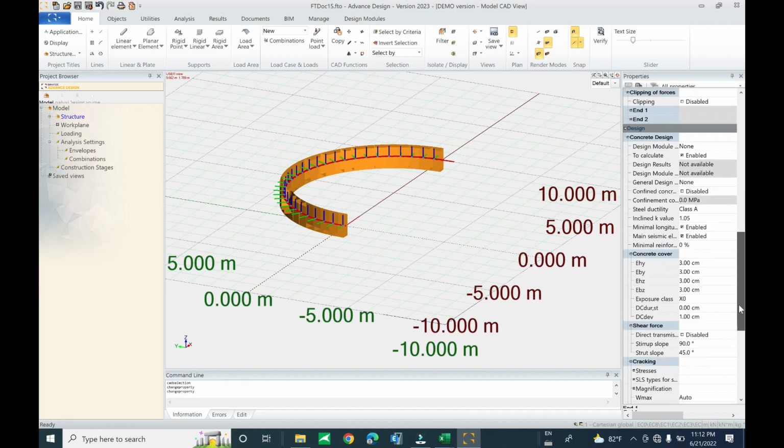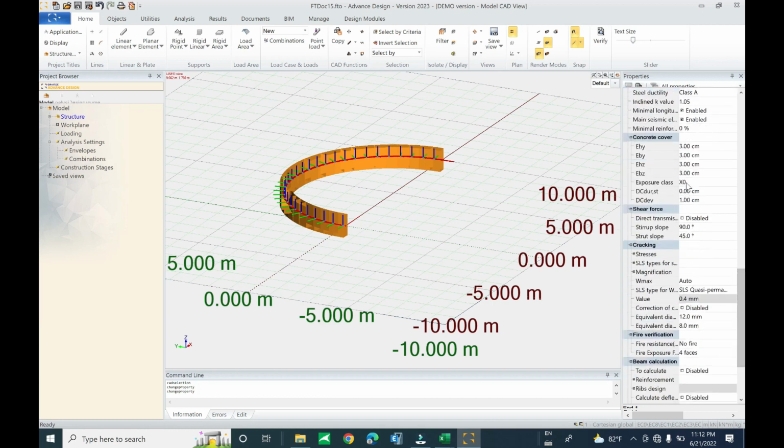on the concrete cover. Now we want to keep the concrete cover in default, which is 3 cm. Incline exposure is 0. Here you can change the angle of strut. In the default software, in Tedds, in Robot, in Graitec Advance Design, all of the software use the same default strut angle, 45 degree for the maximum. For the critical they use shear angle, strut angle 45 degree. Actually this strut angle can be lower than or smaller than this value.